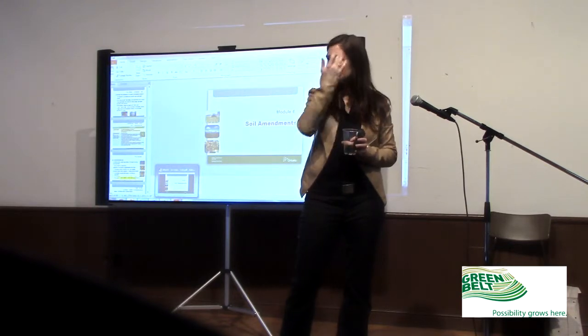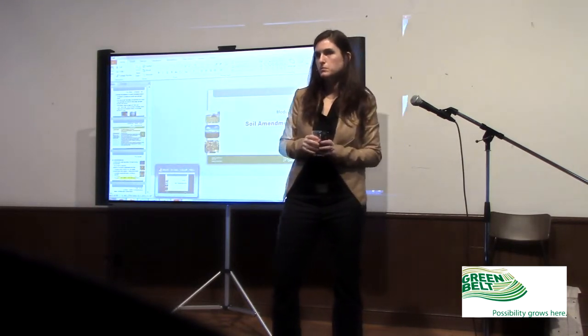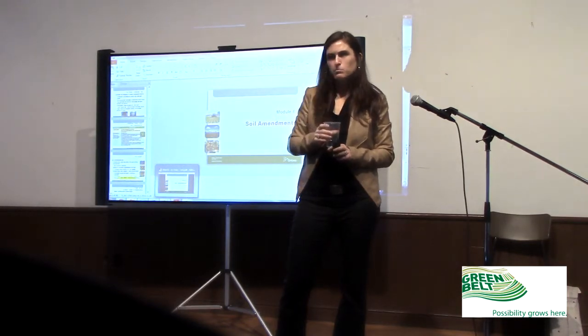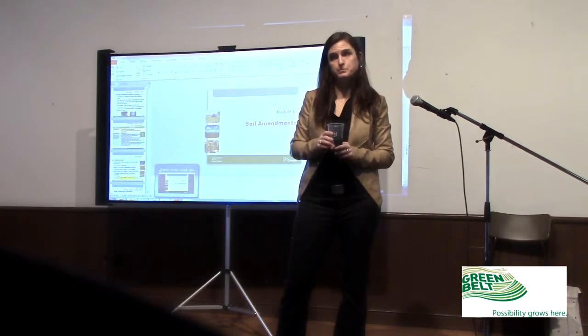There are certain wait periods for any sort of crops when you apply sewage sludge, and it is treated, but you can apply paper biosolids on vegetable lands, but there is a long wait period. It's about a year or two. Well, you can do it in vineyards. They do every second row and incorporate every second row for a 5-year period; you can only do so much. They do that in Niagara a lot with paper fiber biosolids.